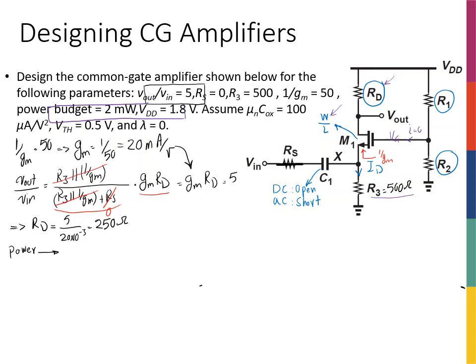From the beginning of this course, we have talked about the fact that all of the signals in the electronic circuits that we discuss are small signals. So the fluctuations are very small, the peak to peak of that signal is in the order of millivolts, so most likely the AC power consumption is going to be extremely small. So we're going to really talk about the DC power consumption all the time, because that's the average power being drawn from the VDD.